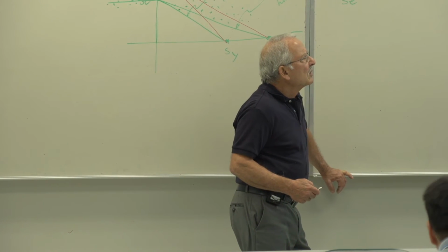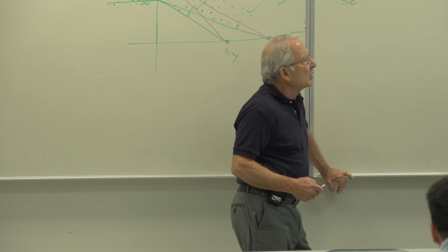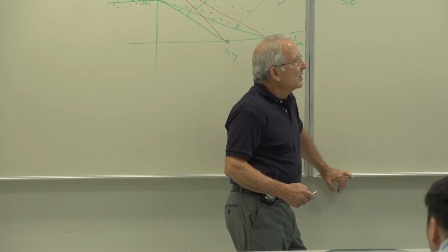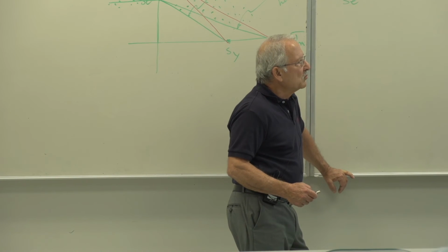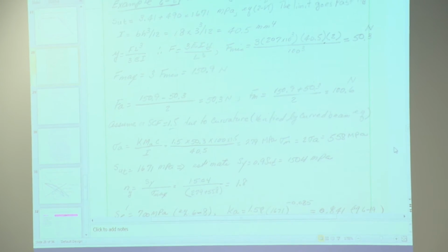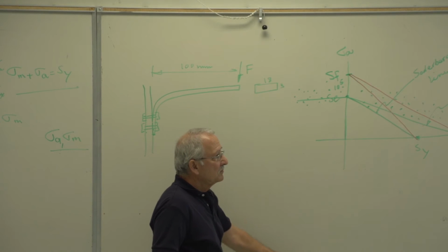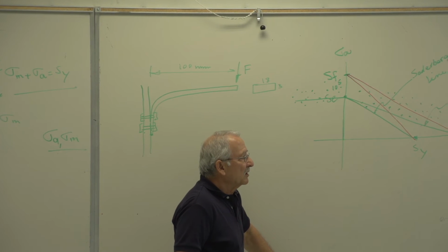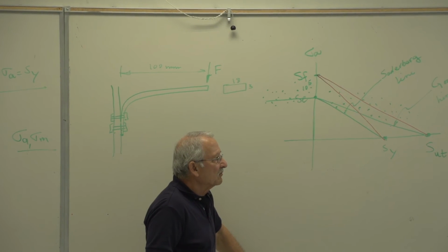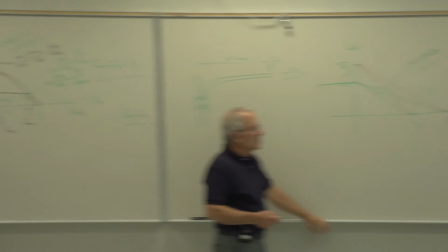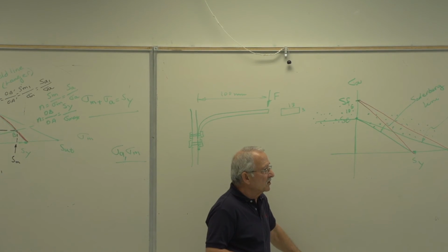Or maybe no, when I use it for fatigue, I think I'll make a correction. This is only for static loading. So K times M, which is 50 times 50.3 times 100. Minimum value of this load is 50.3. Alternating value, sorry, which is the same as the minimum value, times 100 times C, 1.5, half of 3. That's where that comes from, divided by I, 279.